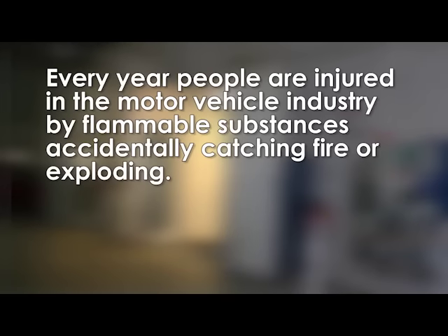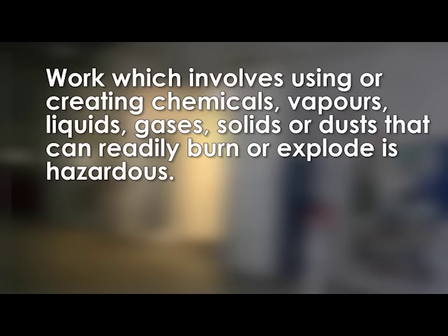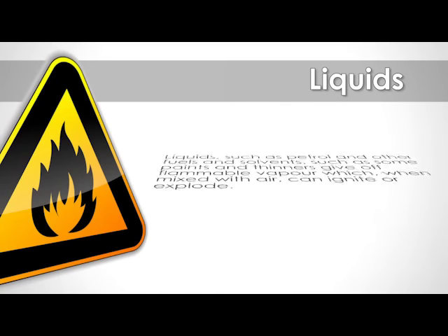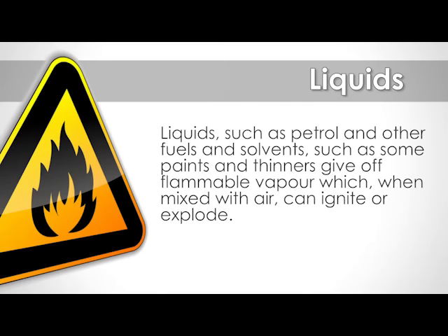Every year, people are injured in the motor vehicle industry by flammable substances accidentally catching fire or exploding. Work which involves using or creating chemicals, vapours, liquids, gases, solids or dusts that can readily burn or explode is hazardous. Liquids. Liquids such as petrol and other fuels and solvents, such as some paints and thinners, give off flammable vapour which, when mixed with air, can ignite or explode.